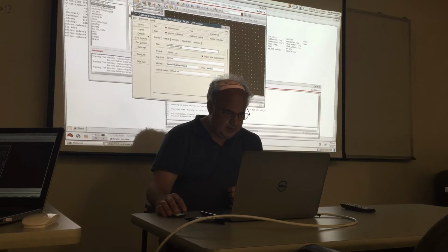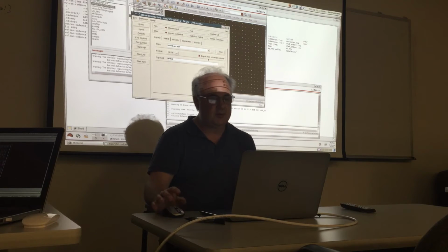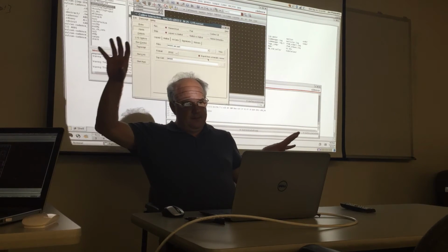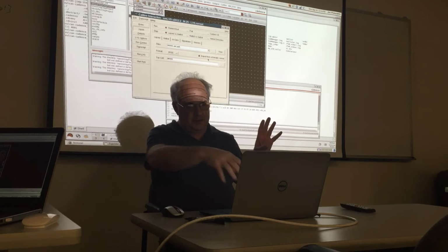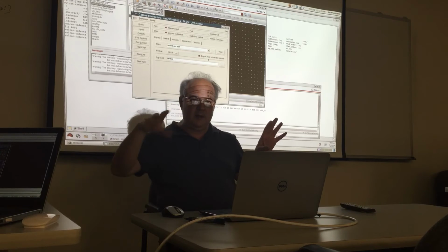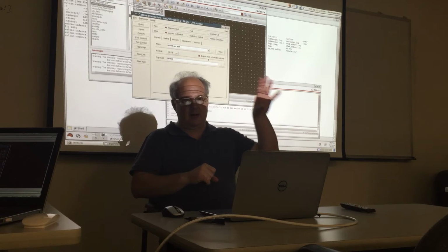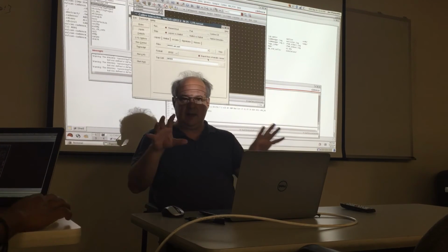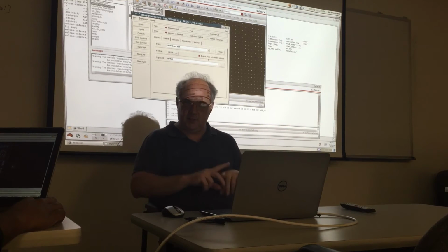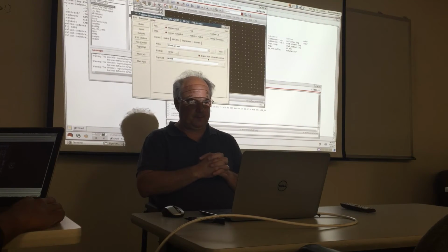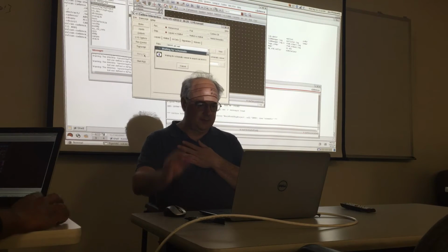What you want to do is take your schematic and create this source.net file, take the layout and create this DB file, and then it does a formal verification of the two. So make sure they're both exported, and hit OK. This one will pass, of course, I hope.